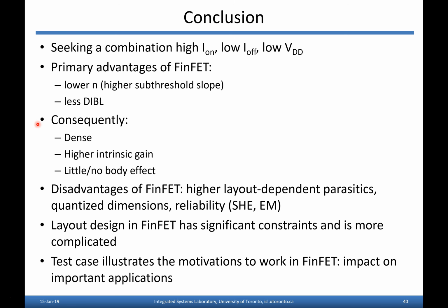As a result, FinFET technology gives us dense logic, so we can cram a lot of functionality onto a chip. We also, interestingly, get higher intrinsic gain for analog design, and little or no body effect, but there are significant disadvantages too. Notably, the layout is complex, and there are a lot of layout-dependent parasitics that are dominant. Reliability considerations, I would say, are also a big deal that impact all the layout styles you have to use. So as a result, layout design in FinFET is a bigger part of the design story. It takes a larger fraction of the time and has a greater impact on the ultimate performance.